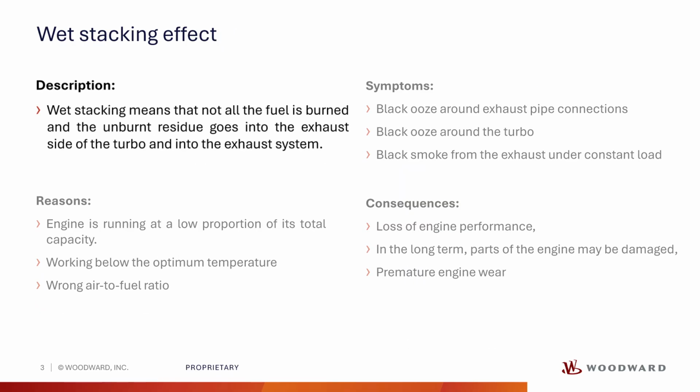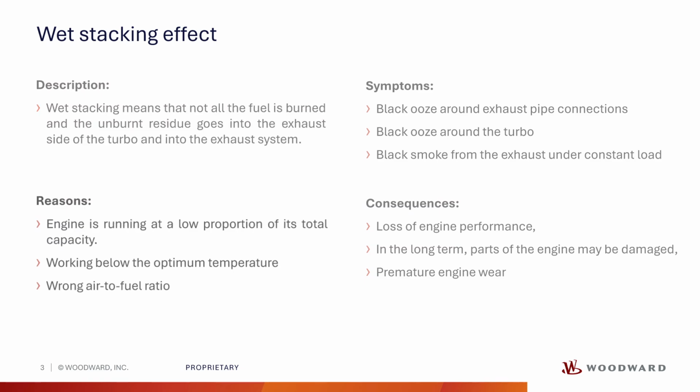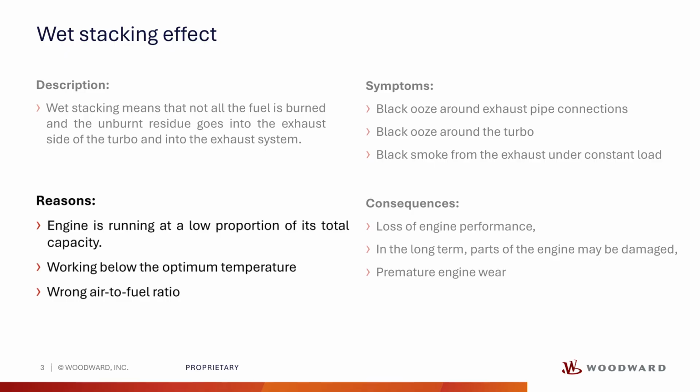Wet stacking occurs when an engine fails to burn all of its fuel. Instead of being burned, the unburned residue passes to the exhaust side of the turbocharger and ultimately to the exhaust system itself. The main reason for this is the engine running at low power.